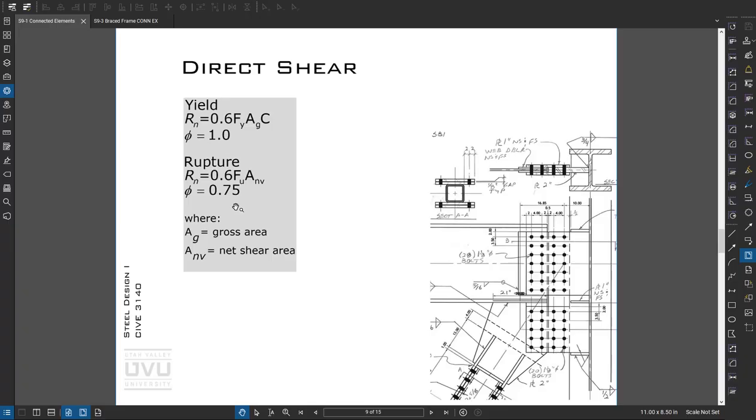So it's basically taking the brace force, creating resultants, tension and shear resultants in the joint, and then just working through piece by piece, each design element. So in the end, a joint like this, which looks fairly complex, can be designed just like eating an elephant, one little bite at a time, until you get through it.